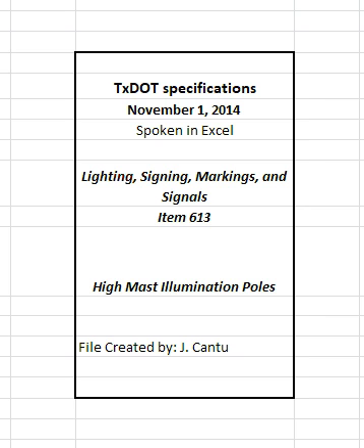Hot dip galvanize fabricated pole sections and associated parts in accordance with Item 445, galvanizing. Punch or drill holes in steel parts or members, when allowed, before galvanizing. Fabrication tolerances are given in Table 1. Provide ultrasonic testing, UT, of the shaft to base plate weld joint with a procedure approved by the department. Perform UT at this joint after galvanizing. Table 1. Fabrication tolerances. See table in specifications.